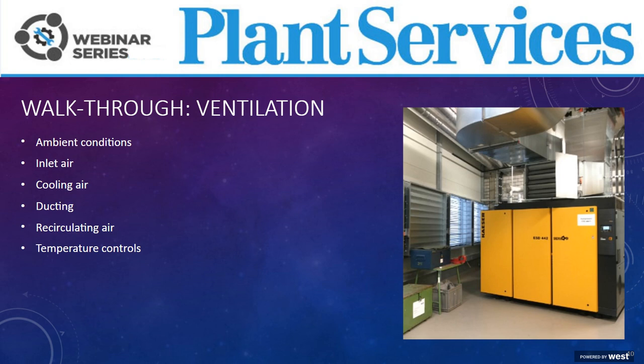Most sites have temperature controls to ensure the room stays between 60 degrees and 80 degrees Fahrenheit via a combination of temperature sensors and actuators to open and close inlet louvers and dampers, as well as recirculating ducts on your compressors. And this is a good practice.